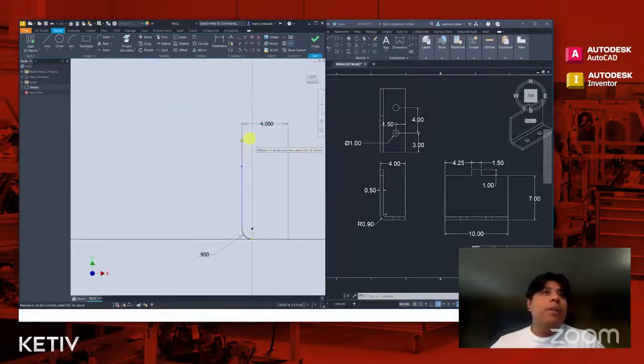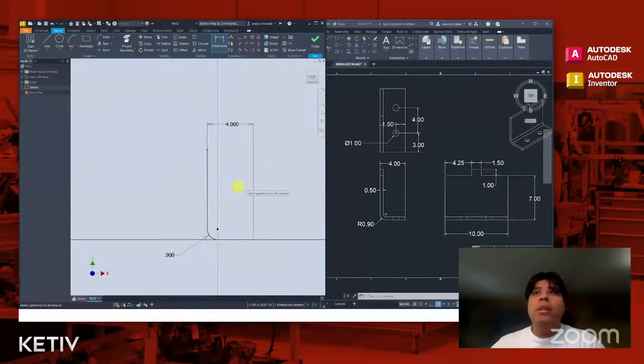And that, I believe, is going to be this vertical. So you can see that this line can still move up and down. So I do still need to add in a vertical dimension or a constraint to finish up this line. So I'm going to add in this last one, which I believe is 8 inches. Okay, so now I created part of this line.